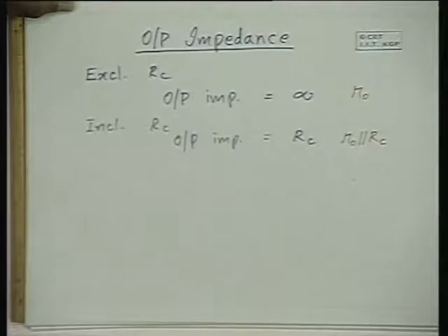We got expressions for these, including R0, in the previous class. Please note that when I discussed the small signal analysis of the amplifier with fixed bias circuit, the equivalent circuit is similar. Therefore, the same analysis holds good here also, where RB is R1 in parallel with R2.